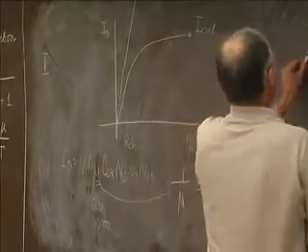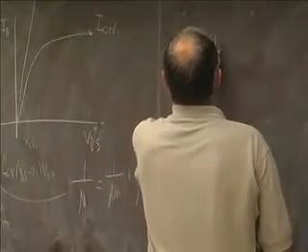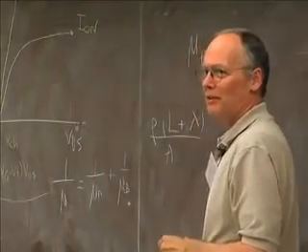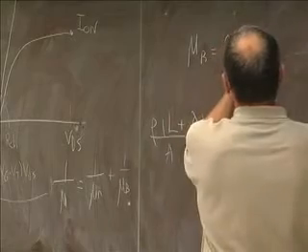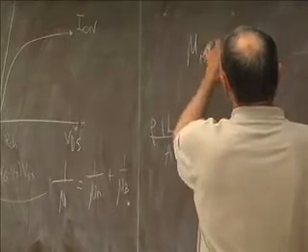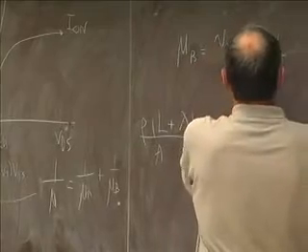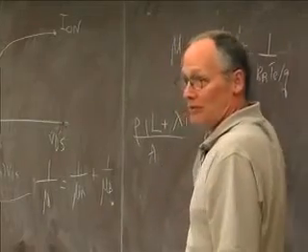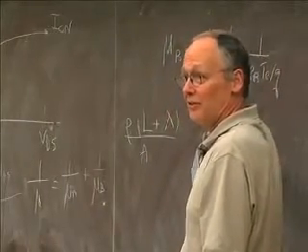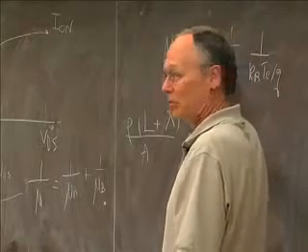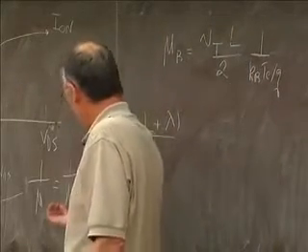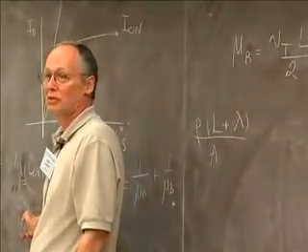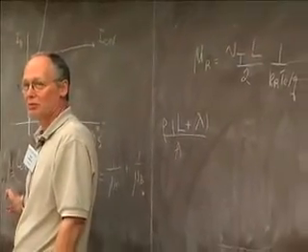So that ballistic mobility is thermal velocity times mean free path, but in the ballistic limit, the mean free path is the channel length, right? Divided by 2, that's diffusion coefficient, and then the Einstein relation divided by KT over Q. So as you scale and get transistors denser and denser and denser, this ballistic mobility gets smaller and smaller and smaller, and it tends to dominate. So you get some boost, but you don't get nearly the boost that you would expect just by looking at the differences in the bulk mobilities.